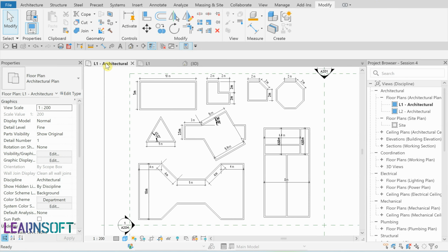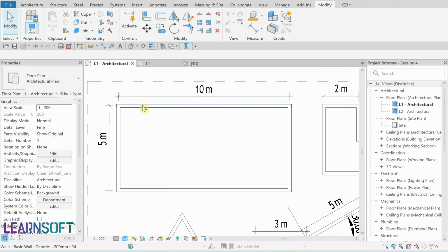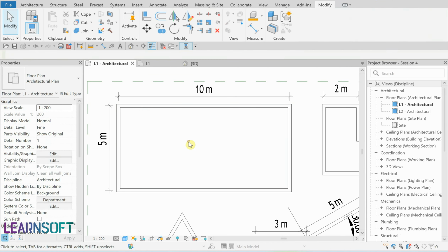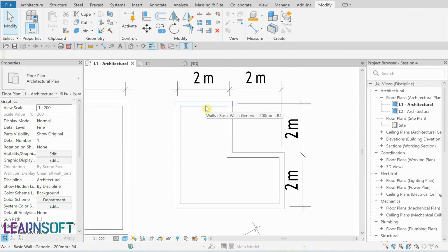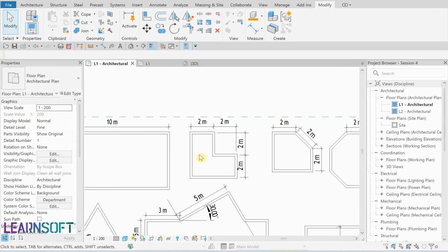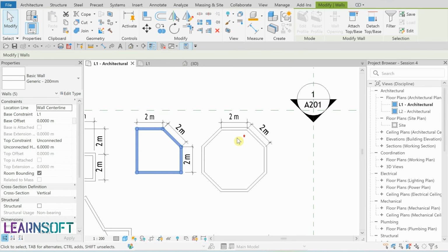Another note about selection is tab selection. As I mentioned before, when you press Tab several times, possible selection candidates near the mouse sign will be shown. This allows you to select exactly the one you want. If any chains of connected elements are near the mouse sign, they will be included as candidates. Let's practice more and select the connected walls or closed shapes by tab selection.